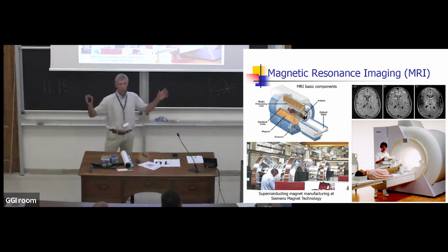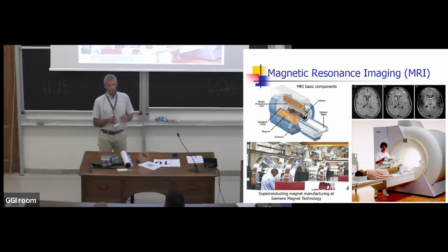So MRIs work thanks to a big solenoid that produces a horizontal field on the patient, very homogeneous in the zone where you want the resonance to take place. Then you use antennas and gradients to generate a point of field, and you tune into that frequency so that you can essentially slice the patient with magnetic field points, voxels, and then you reconstruct the amount of water, as an example, that corresponds to a certain position in the patient. So these are the images that get generated today.